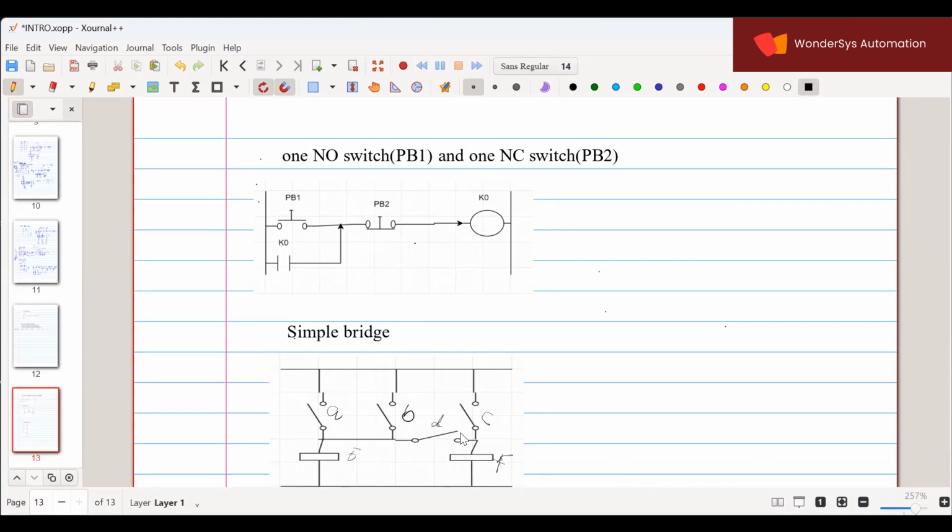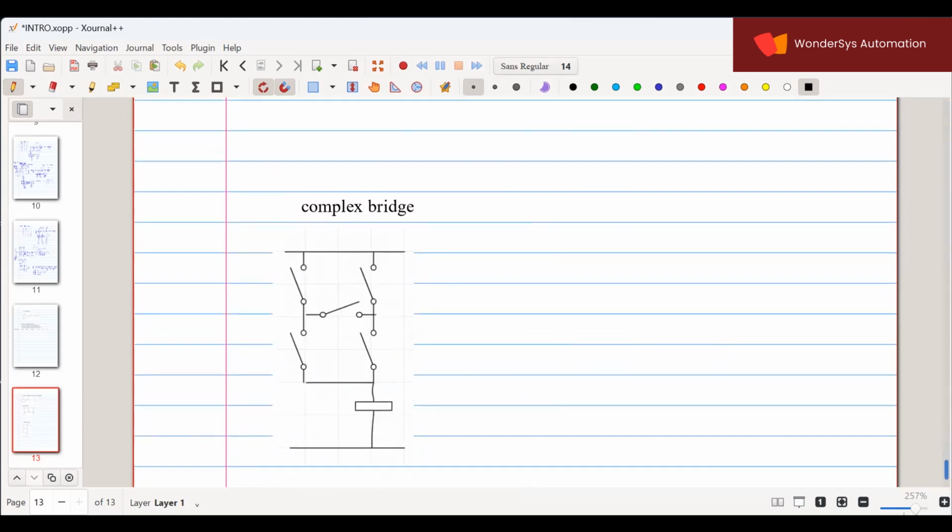And in the second condition, it exactly looks like a circuit. Don't make it look like a circuit. But the last one is correct. But don't make ladder diagrams like that. It's hard to understand. You can repeat the addresses, okay? You can repeat the address. For reducing the addresses, check it out. How can you do it?